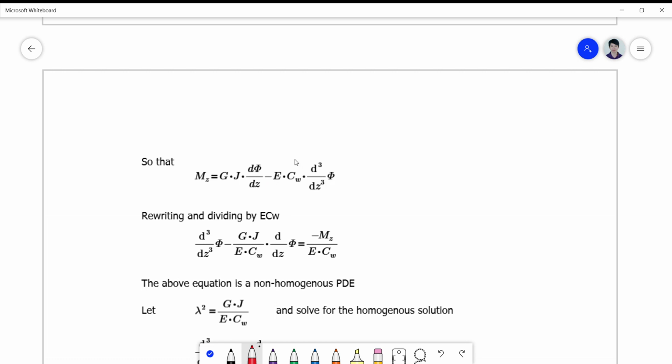I'd like to emphasize that the negative sign here, which is sometimes confusing, only indicates, on the lateral bending, that your direction, which is your z direction, is opposite the convention used for positive bending, which is upward.